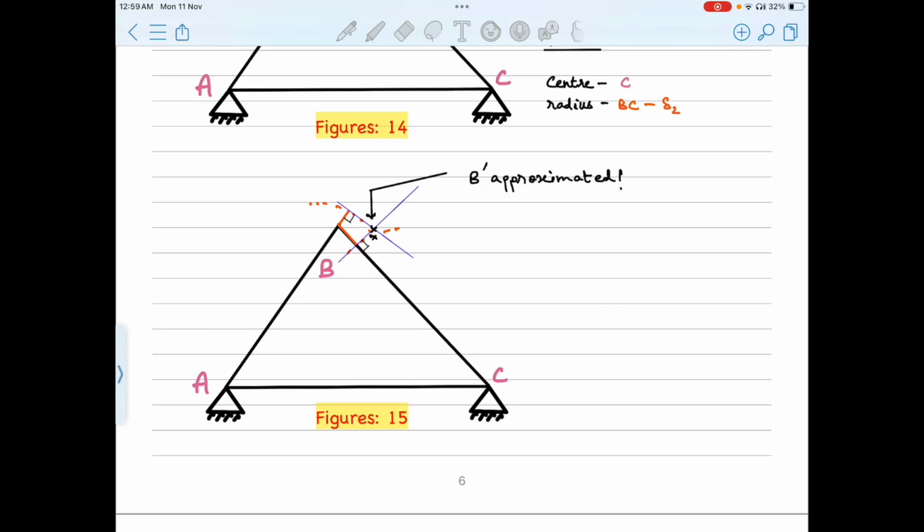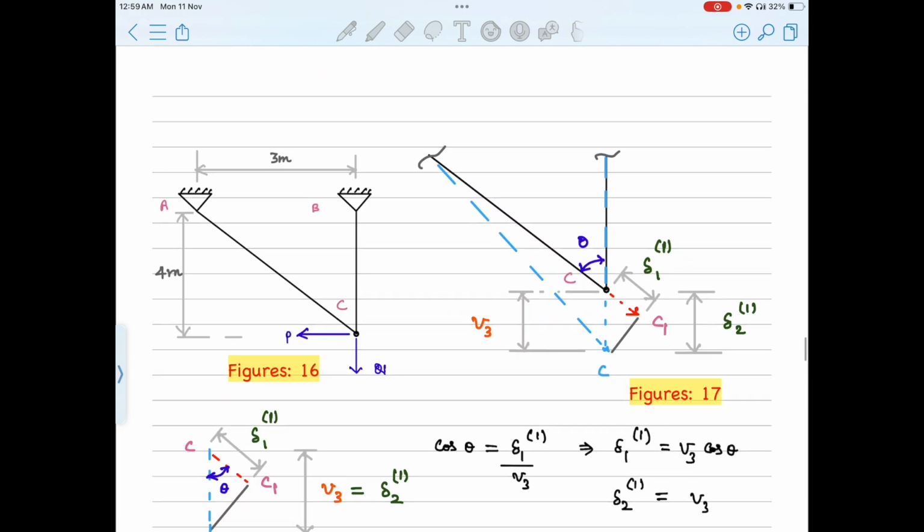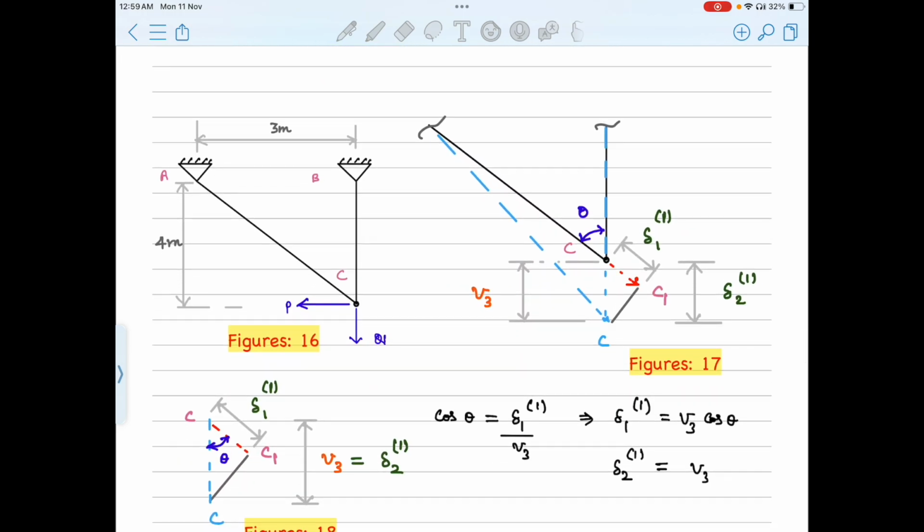So the idea here is if we know the deformed length of each member, we can draw these tangent lines which are perpendicular to each member. See, this tangent line is perpendicular to member AB and this tangent line is perpendicular to member BC. We can get the desired result with the accuracy required. Now let us go back to our original problem. We said we already used the stress-strain relation and strain-displacement relationship. Next, we are about to include the compatibility requirement.